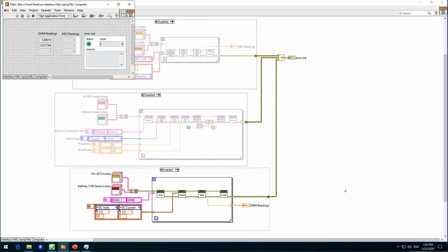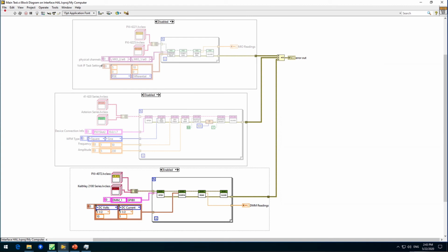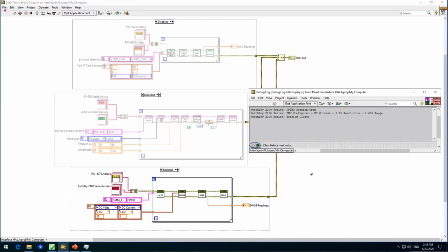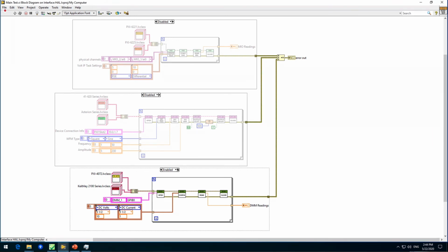What we've done is we've ended up with 2 DMM readings, and we've done all the DAQmx stuff with no error, and we've done the Keithley benchtop stuff. Obviously, I haven't got the 2020 version of that driver, and I haven't actually got that DMM on my desk. But you can see we defined the sessions opened. This is taking the class name that's overridden the interface, and then the function that is provided. So you can see we've configured and then closed. That's really showing two similar types of class that share a general interface.